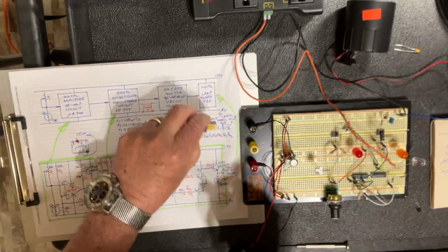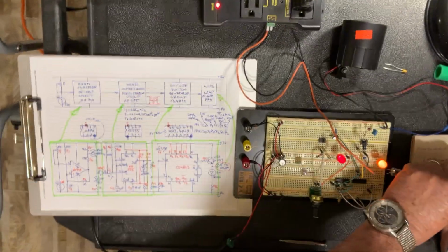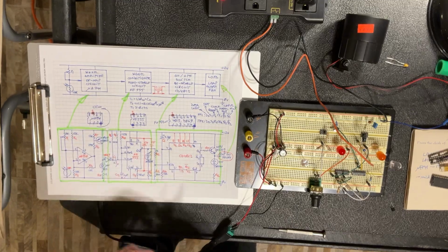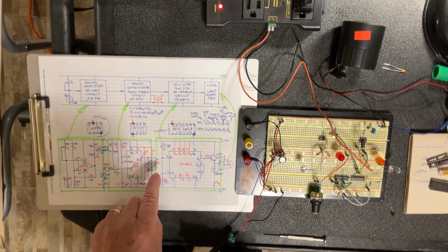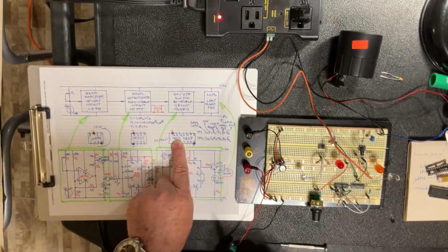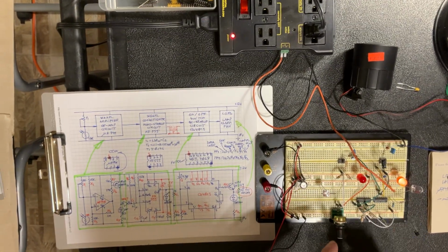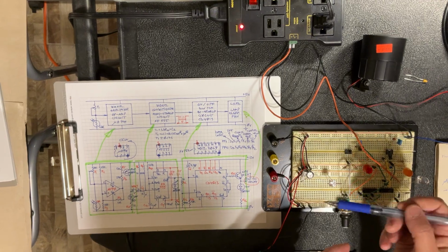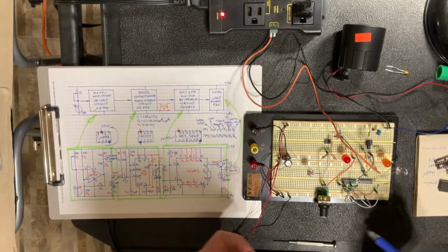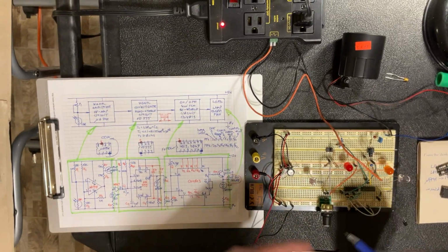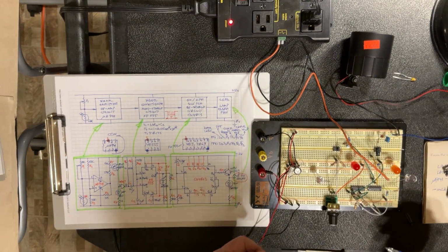Okay, so now we know it. And I'm going to talk much more about these kinds of things when we start talking about the logic circuits. So that's how we connect the package physically. I put them in such a way that all the packages are aligned with the notch to my left, so it's easy to identify where pin number 1, 2, 3, and so on are for each of them. Okay?